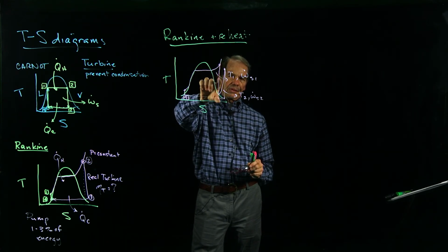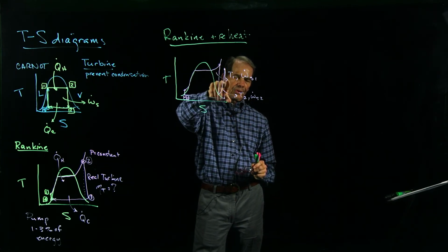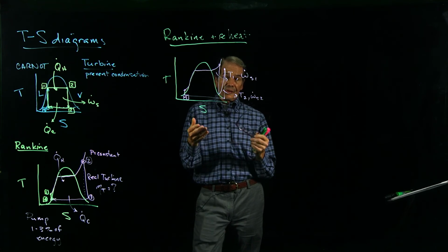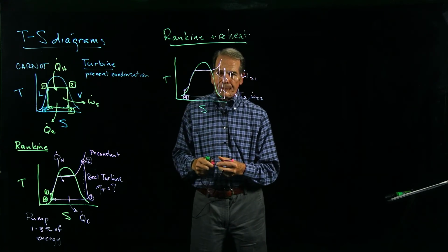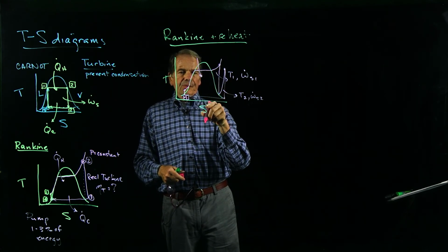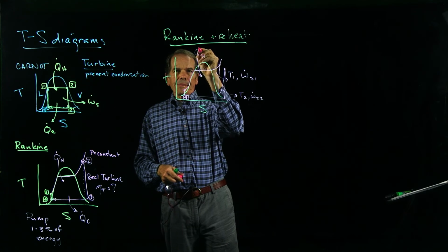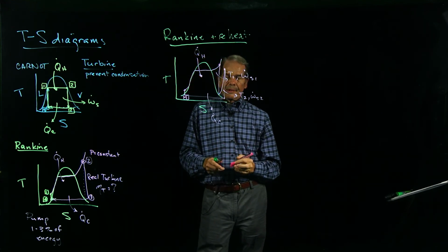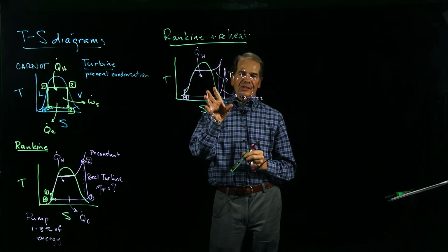But this pressure difference may be a factor of 4, so this will still be running at the same temperature coming in, but at a lower pressure. Therefore, you're going to extract less energy from the steam, but you're still getting that energy out, which you didn't get out before. And then you're rejecting heat to the low temperature side. And so this improves the efficiency of the overall system terrifically, and it recovers critical heat.